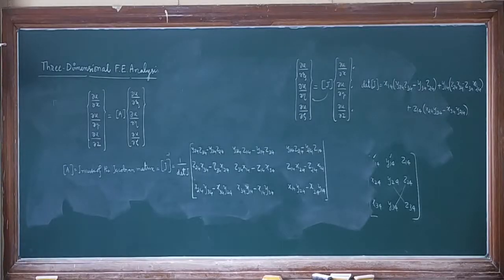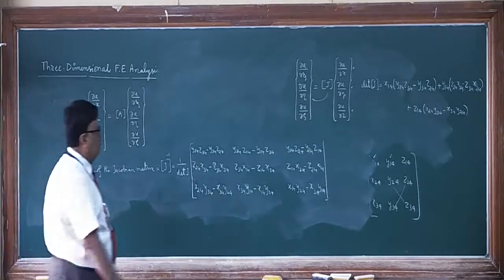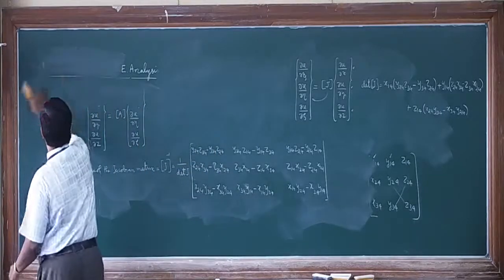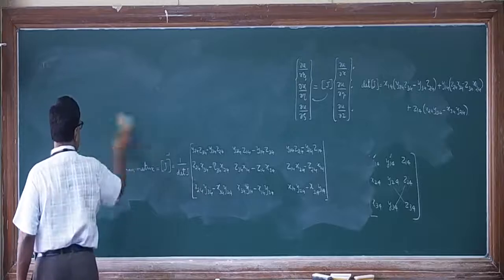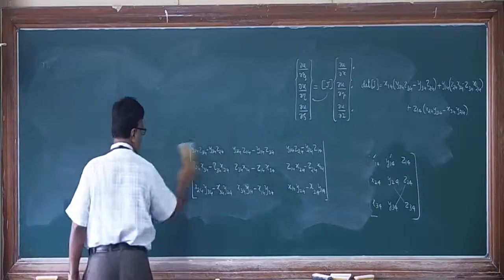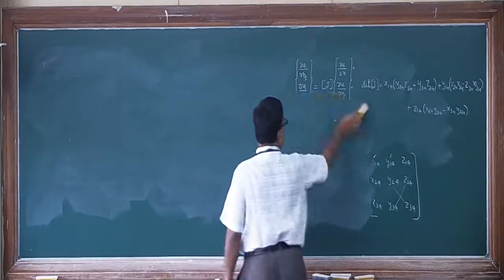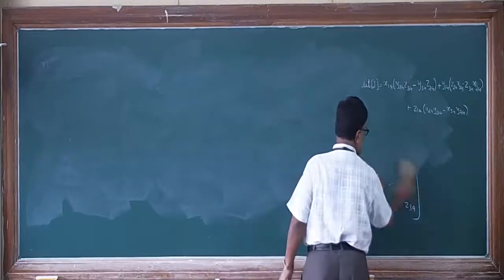So with this, since you know that the displacement vector is related to the displacement at the nodes by u equal to N q, and with the substitution of all this, I will be getting a 6 by 12 element strain displacement matrix B. So let me write that. That is going to be a very big expression. We will just copy that. Here it is more of a copy, because all the expressions are mathematical in nature. I just cannot dictate it on video now, so I need to write, so that you can read these elements, copy them down on paper and practice this.